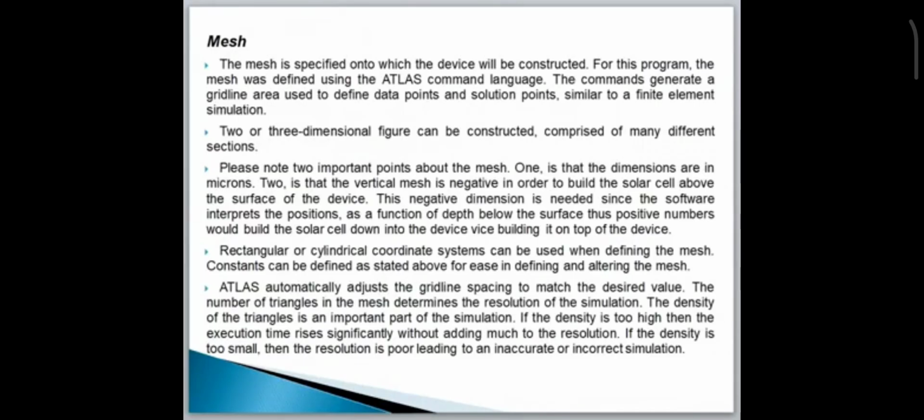After defining the constant, we have to define the meshing. The mesh is specified onto which the device will be constructed. For this program, the mesh was defined using the Atlas command language. The commands generate a grid lines area used to define data points and solution points, similar to a finite element solution. Two or three dimensional figures can be constructed comprised of many different sections.